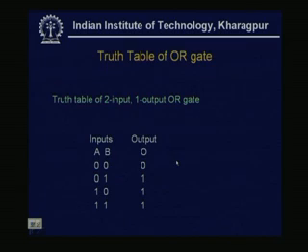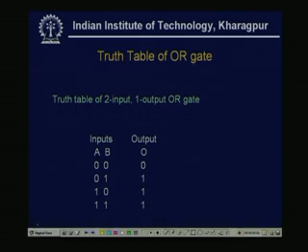Okay. Then what will be the truth table? See in a similar way, this is a 2 input A B and output O. So, again if we draw the OR gate, this is a 2 input OR. Now, input lines I have given A and B and output is O. So, if A B is 0 0, then both switches are disconnected. So, output will be 0.